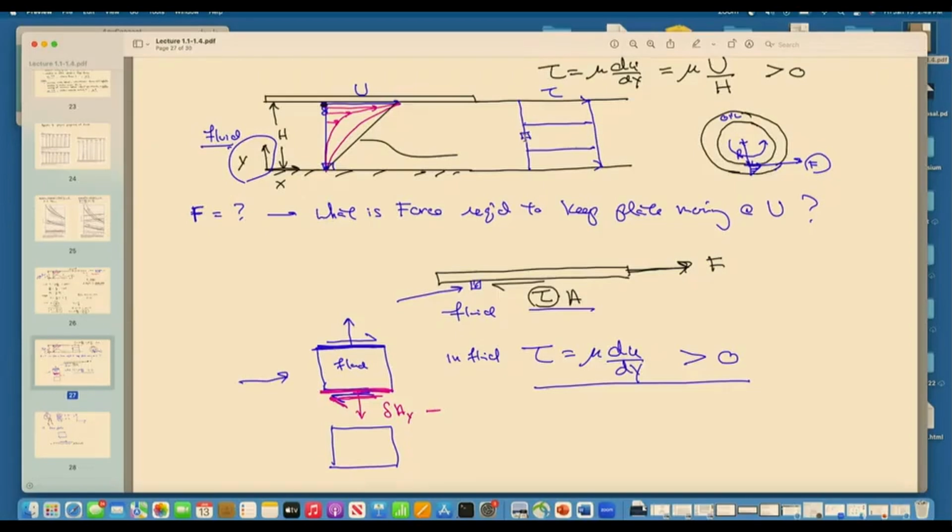So there is this rate of volume change, or dilation or dilatation, and then there's just the translation of a fluid element as described by its velocity. We're going to discuss all of that later as well. It's all related. The vorticity can be evaluated by the velocity gradient, and in fact, it is the curl of the velocity, del cross v.